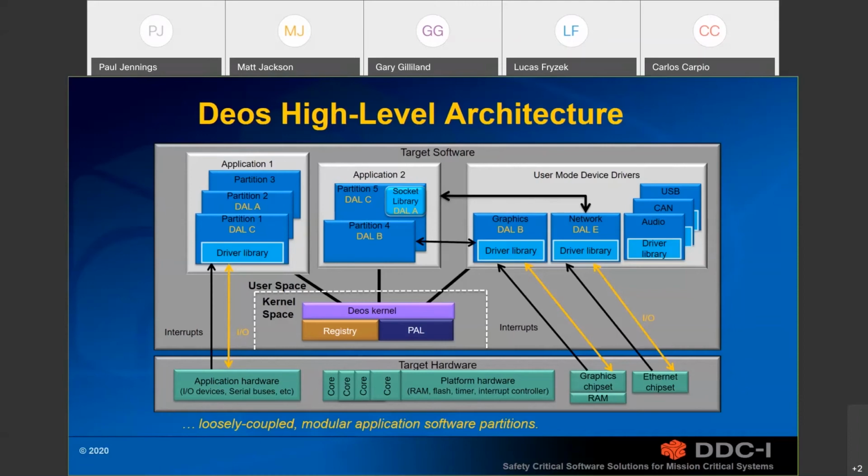So that's key. Up above that, you can see that in our case, most of the drivers are typically in user mode. There's a couple of reasons for that. One, it's easier. It makes them just like any other application. Another one is you can design them to the level, or the DAL level, that's required for that particular interface. If you include all your drivers in the kernel, then those drivers have to be designed to the same level as the kernel. Therefore, it costs more, there's more time, more energy, more risk, and that kind of thing. So we feel like this is a better model.